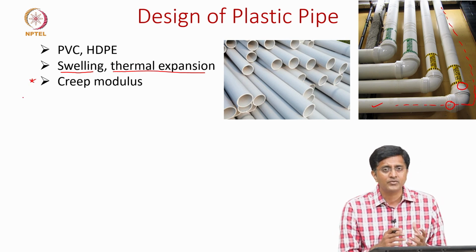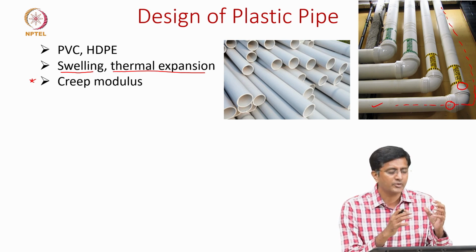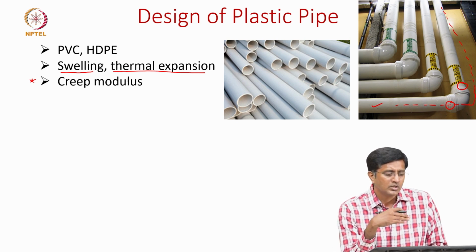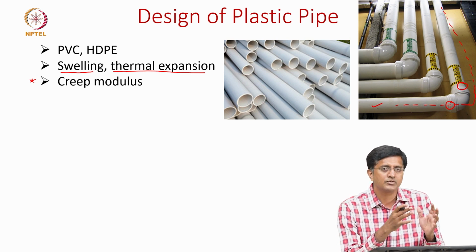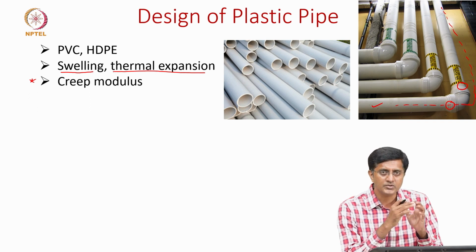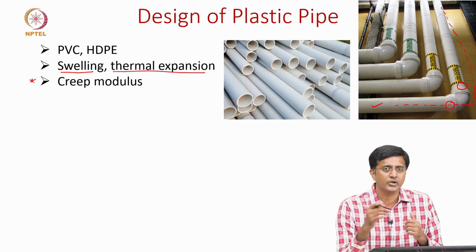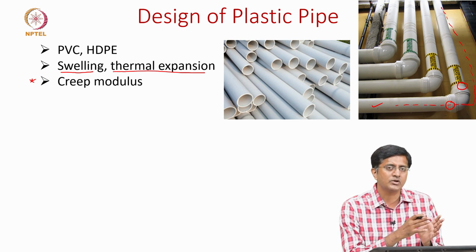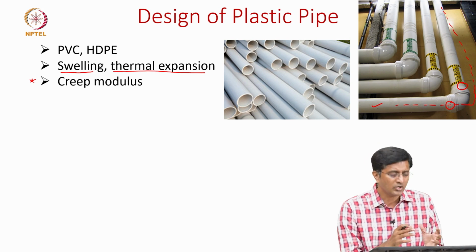So, depending on the kind of loads, as we all know, the creep modulus changes with time. Initially, it might start with a high creep modulus, but over the time the modulus values decrease. So, depending on the loading, whether you are looking for short periods of time, then you look at short term creep modulus, but if you are looking for a long periods of time, of course then we look at the long term or the equilibrium creep modulus. But depending on again whether these are seismic loads or whether these are occasional loads, it all depends.